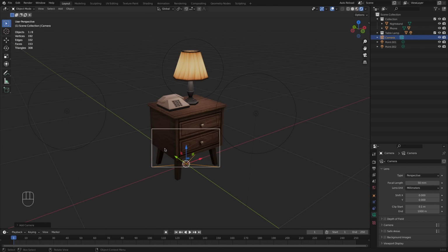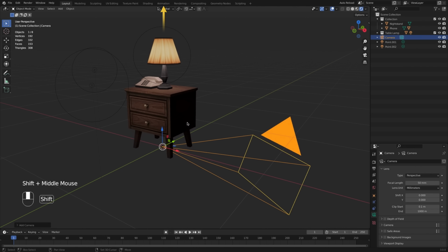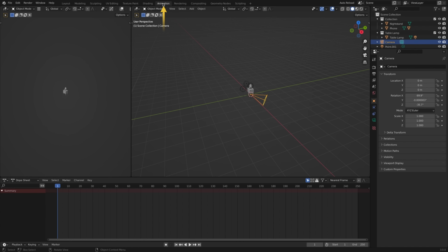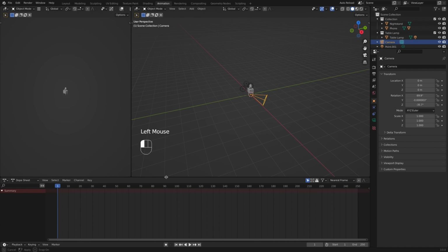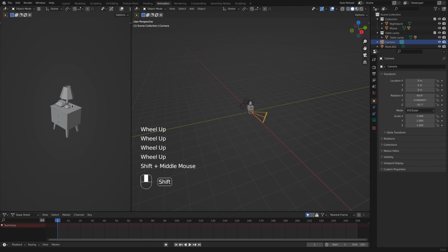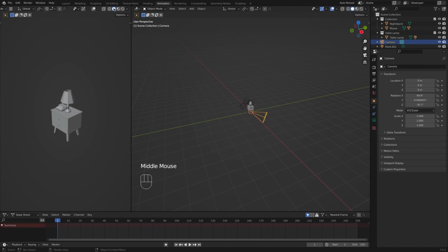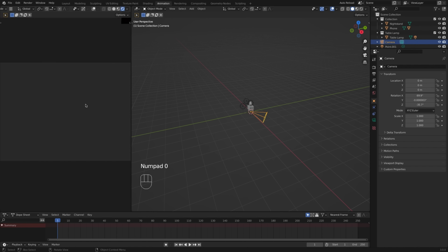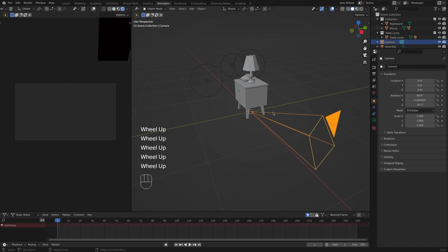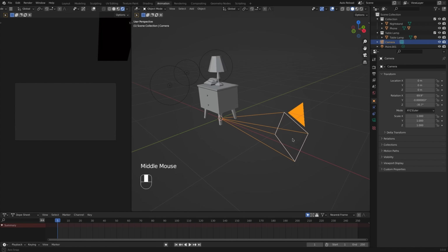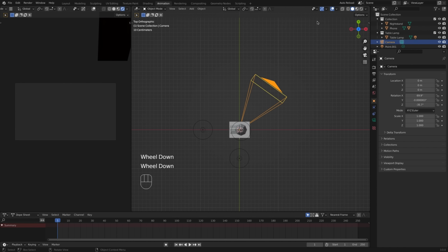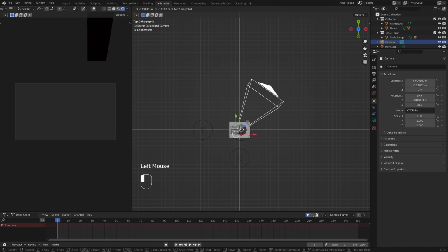And then I'll switch to animation in the top menu, since it is more convenient for me to work with the camera. On the left side, switch to render preview, then press 0 to go to the camera view. Now in this rectangle we can see a gray background, just because the camera is pointed somewhere down by default. You can try to move and rotate the camera manually, like this.